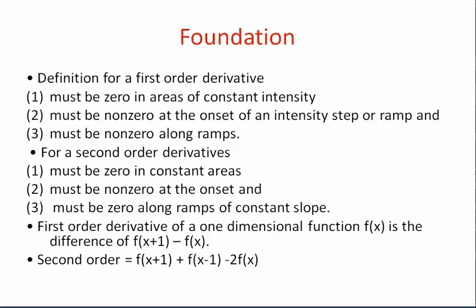Differentiation is used for sharpening an image. That's why you should concentrate on differentiation. So here is the first order derivative and then the second order derivative. This is a very important basic thing; you should know this. We apply the first order derivative technique or the second order derivative technique on the image. One is said to be the Laplacian operator, another is said to be the gradient operator.